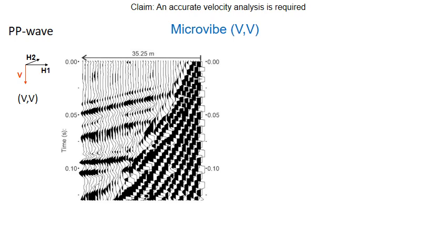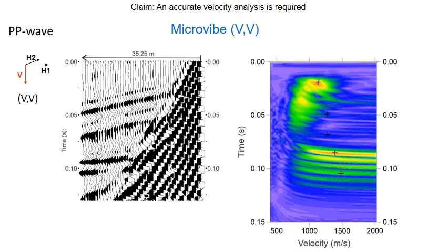On the same location as in the shear wave record from the previous slide, here is a raw P wave record acquired in vertical mode. Based on my experience, the P-wave has always been easier to pick in a semblance analysis as the error margin is larger. But here, for example, one has to use his own experience to not pick those near-surface multiples instead of picking direct P-waves or reflection energy.